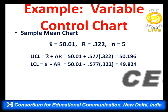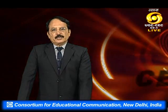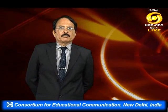Now, upper control limit X double bar plus A R, this is a formula we have already discussed, and this will give us 50.01, which is the mean value already established, plus 0.577, the value of A taken from the table, multiplied by 0.322, which is the average range. The value becomes 50.196. Similarly, lower control limit X double bar minus A R, and we calculate this the same way as the upper control limit, with the difference that the minus sign is used, and this value is 49.82.